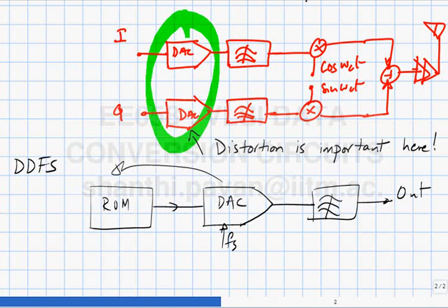So once you have that, in principle you can build a sine wave source whose frequency is programmable all the way from 0 to about fs by 2, by simply using one DAC, and the precision of the sine wave, since you have a 14-bit DAC, will be guaranteed to be about at least 80 to 90 dB.